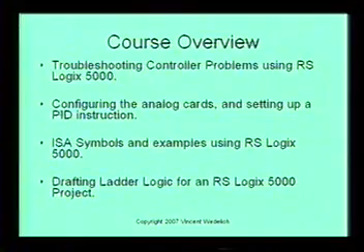It's certainly a good idea to do this if you are unsure what is causing the fault. Typically, when I do a PID instruction, I know I'm going to get a fault when I first download the processor, until I get the PID values at their correct range. If they're out of that range, it'll fault that PID instruction and shut the PLC down.